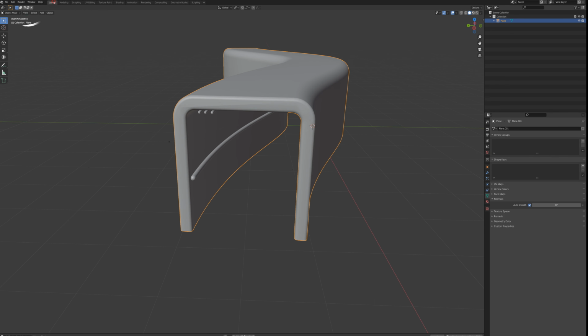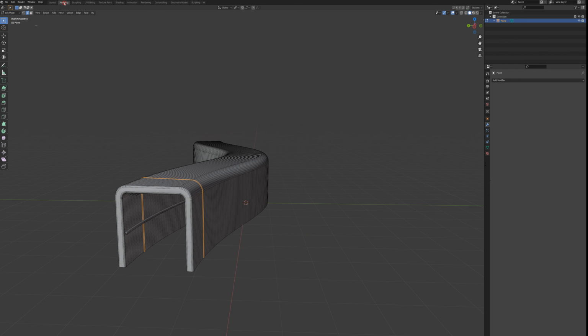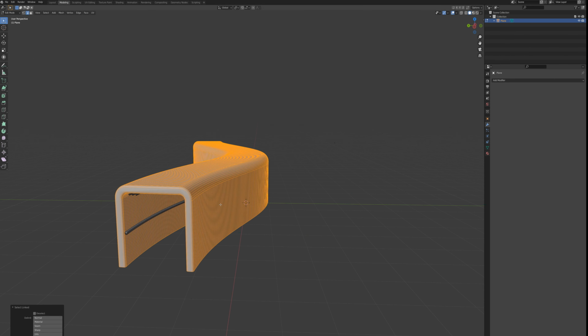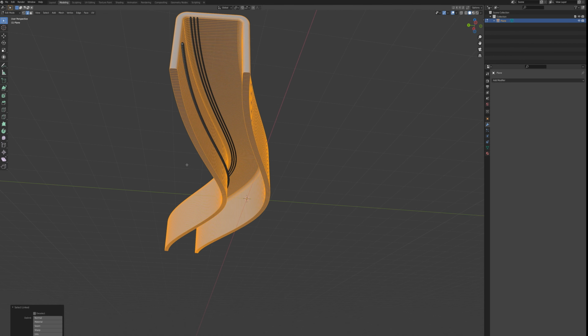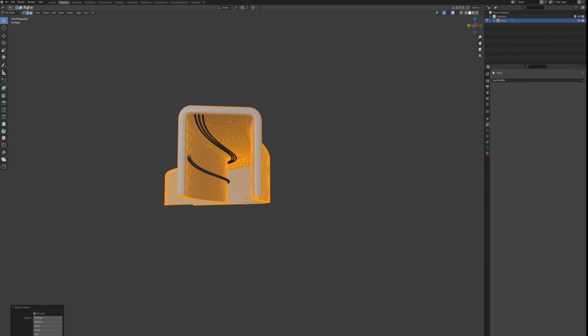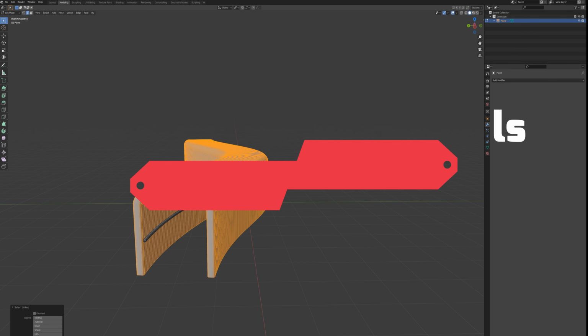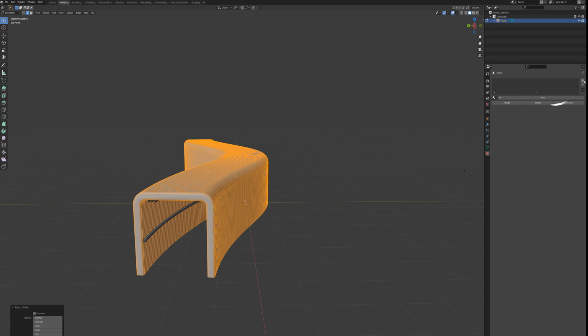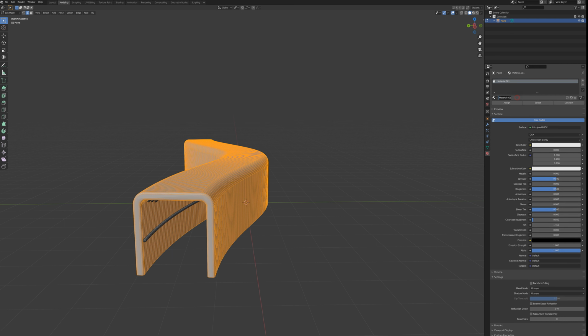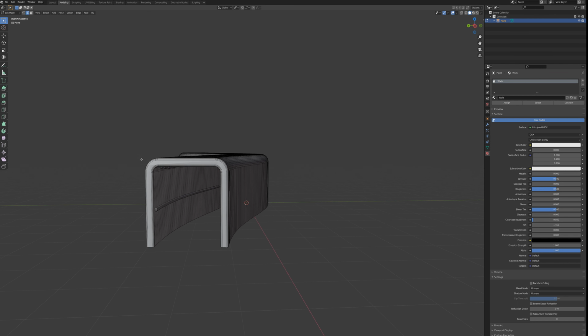So what I can do now is go to layout, modifiers, add a modifier, weld, and apply. We'll go back to modeling mode and press L, hovering over my outside mesh here. And now I've selected basically all of this mesh except for the railing and the pipes up here on the roof. And so I'm going to go to Materials tab here and make a new material, new, and call this Walls, and click Assign.